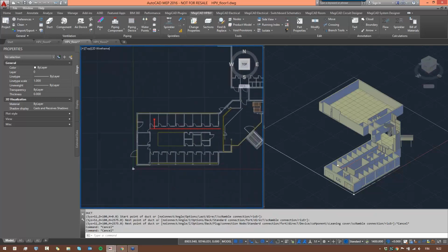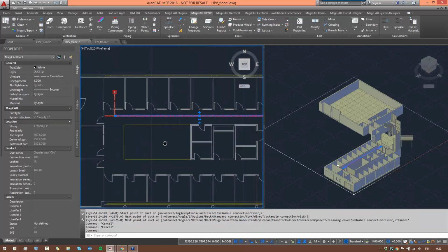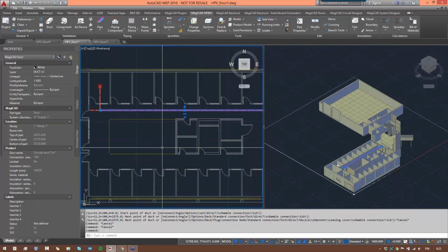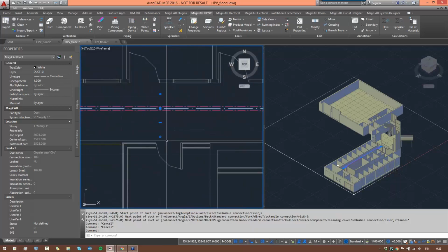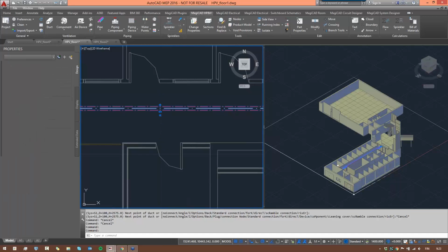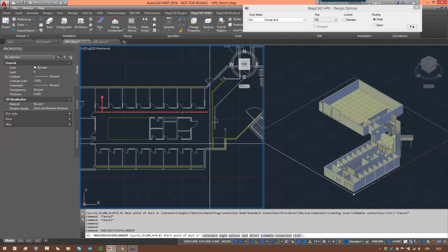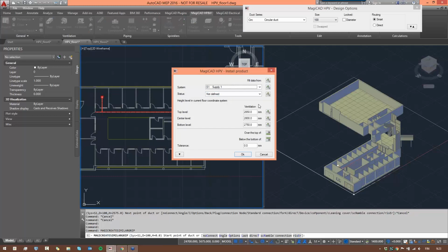And yeah, let's do a similar network on the other side of the office as well. When we have these plus grips here, plus would be add duct or a branch. In this case, there's the move part also, and then there's the create similar. I'll create a similar duct segment there. No, good.